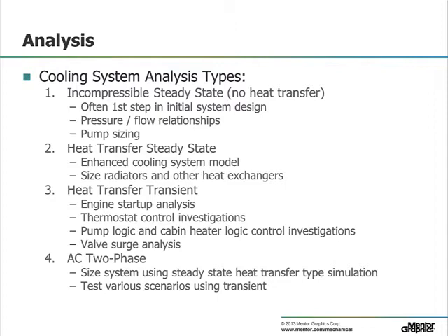With newer technologies such as electric pumps and valves, a lot more transient work needs to be done. As a result, when we start doing hybrid cooling systems, there will be more transient scenarios to consider. In addition to traditional cooling loops, in electric hybrid vehicles, we now see two-phase systems becoming more prominent in modeling the overall system. Flowmaster has the capability to model these two-phase AC systems in both steady state to size the system and transient to see how it behaves for a desired drive cycle. In Flowmaster, an engineer can also see the system interactions between the cooling system and the AC system.